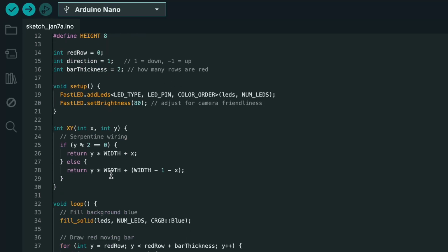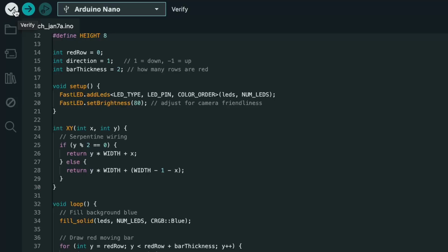All right, so now that we got that all set up, our board's connected to the computer, now we can just hit this check mark here, to compile the sketch. Speed this up, it might take a few minutes. Oh, there, it's done. Then we're going to hit this upload button right here. Should compile it right to the board. Done compiling, uploading, done uploading.